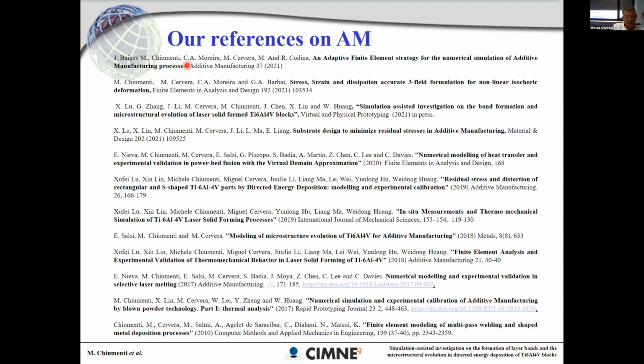This is really depending on the number. The framework is fully parallel and is very much scalable. So it really depends on the number of processors that you have available. Typically, we are running in a cluster with 50 processors, and all the thermal simulations that you saw run in a few hours. If you move to mechanical analysis, you can multiply by 3.